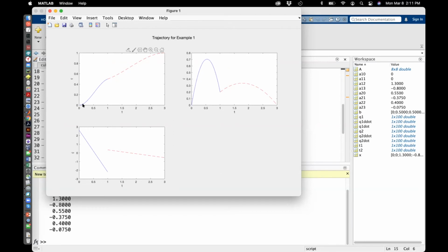You can see that the position is continuous. The velocity is also continuous; it is 0.2, exactly midway at t equals 1. The problem is with the acceleration: at 0, you would suddenly get an acceleration of 2.5, and then it decreases, and then it suddenly jumps from minus 2.2 to 0, which introduces bad things onto a motor.